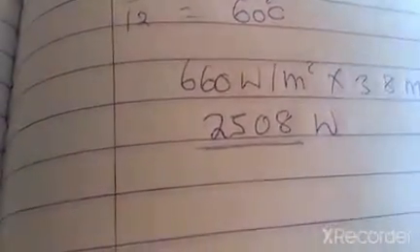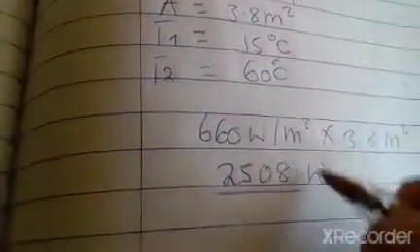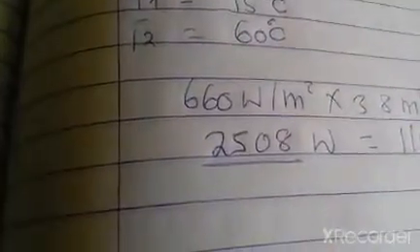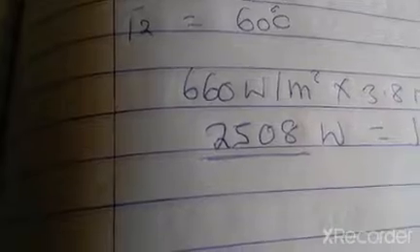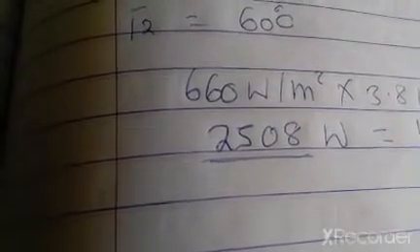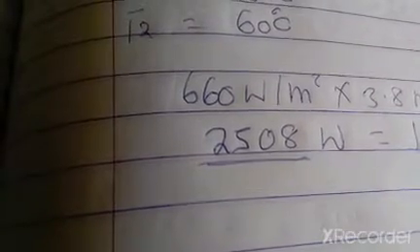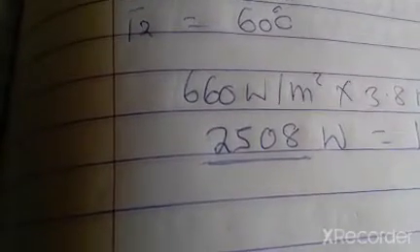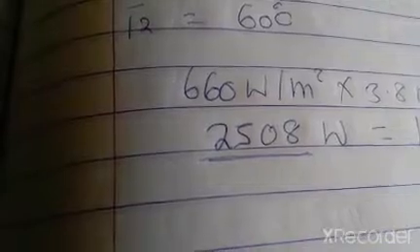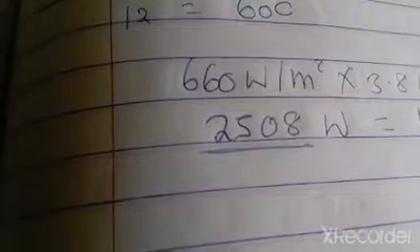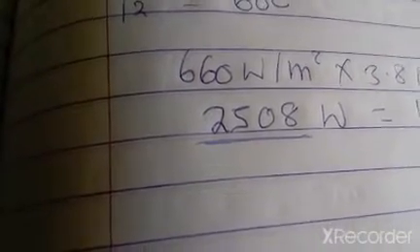So this is the total amount of watts or energy that we are going to absorb with this collector, the total energy. This is in watts, meaning this will be equal to joules per second, isn't it? Now we want to find out how much of the mass we are going to be able to change the temperature of, from 15 degrees to 60 degrees, with this amount of energy.